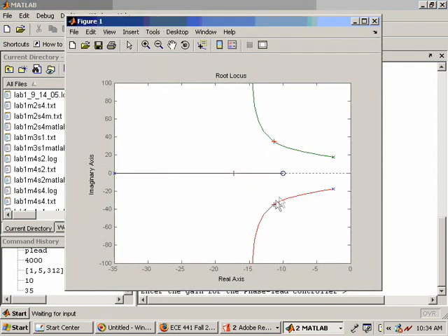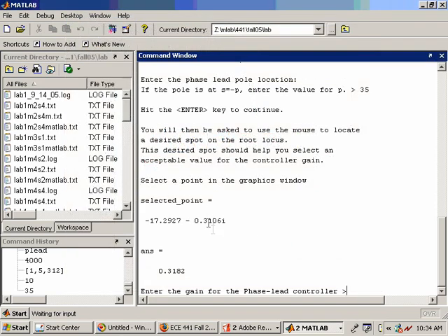And the closed loop poles are now roughly at -11 plus and minus j, probably whatever we calculated in the earlier part of our discussion. Let's just pick a phase lead controller of 0.3. It won't quite put us down at -17.3.